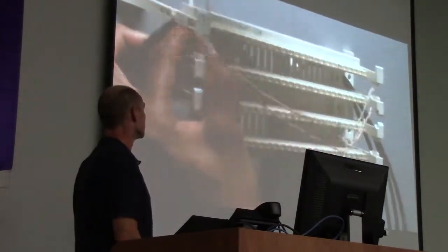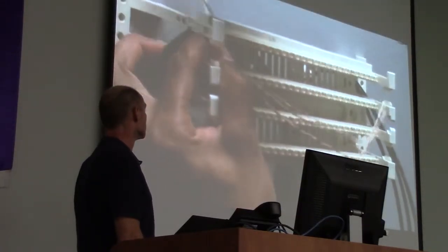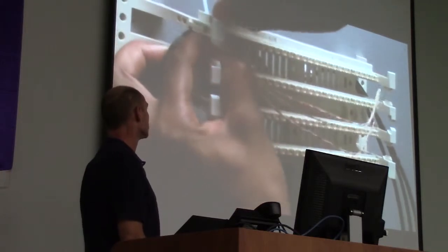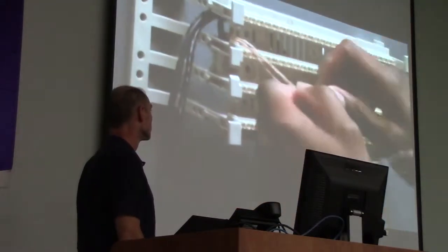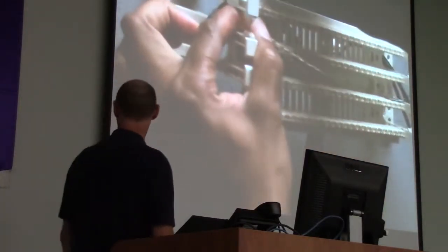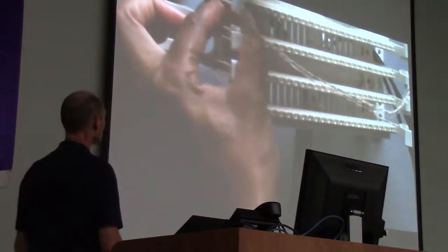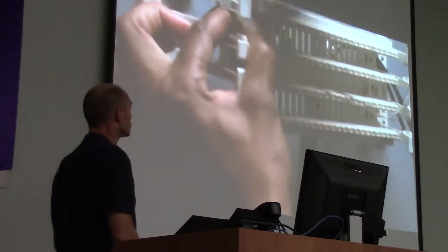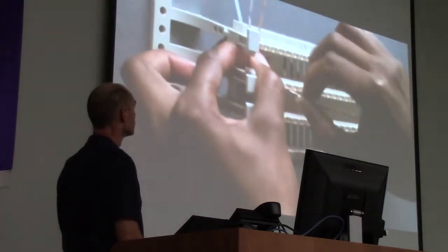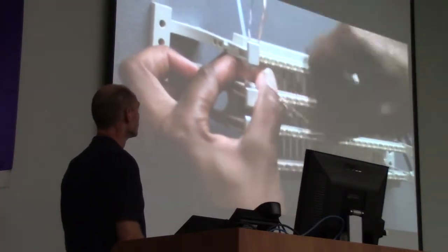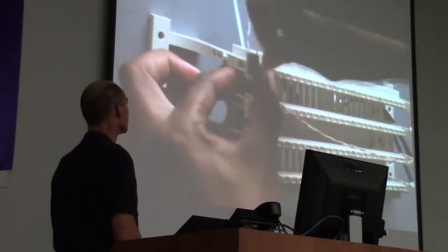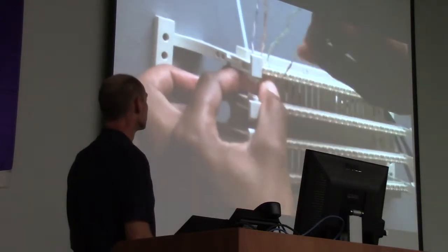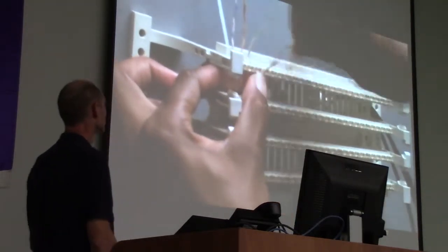That will be blue. Start with your white blue and blue. White blue is the tip, blue is the ring. Go with orange, white orange, orange. So, green, white green, and green. Brown, white brown, brown.